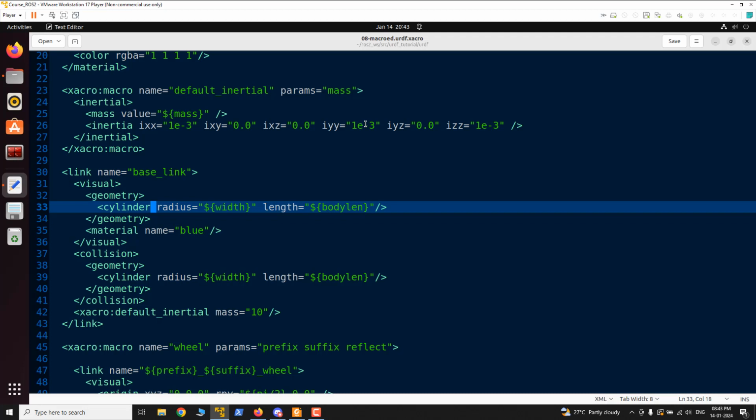If you are converting directly to the URDF, you have to customize it somehow, like adding some plugins. At that time, if it is not a Xacro file, it will be difficult. So maybe you can try first with the plain URDF, add the simulation stuff and all the stuff, and then work on it. If it is good for you, that is fine. But if you think it is taking time to customize, then better to change into Xacro. Modularize it, so it will be helpful, I guess.